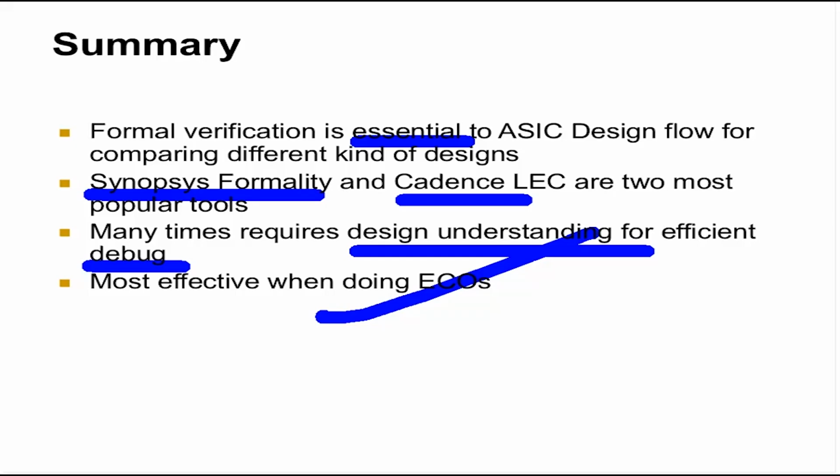Is it desirable? No. What it means is that if a change is simple enough, let's say adding an AND gate, ANDing 2 signals, then you change the RTL on one hand, and then you modify the post layout netlist on the other hand. You don't do synthesis. You modify the post layout netlist directly. This is called an engineering change. This is called an ECO. Formal verification is the best way to verify this. There is no other good way in fact.